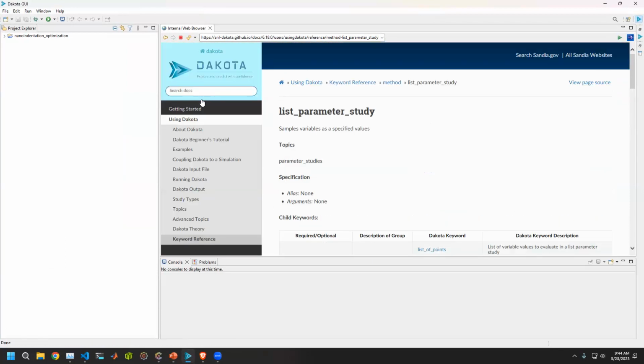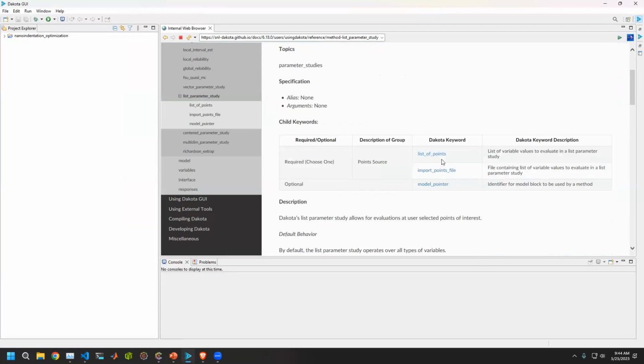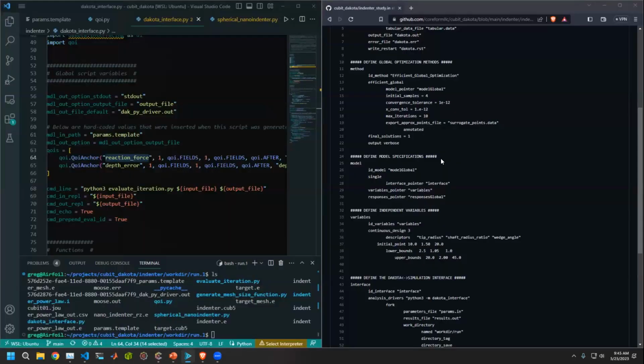But if I specifically have maybe 35 specific models I want to run, I can just put them in as a text file or as a list of points and just let DAKOTA handle all of the directory creation and cleanup. So that's really what I wanted to show, that there's a lot of functionality within DAKOTA that could probably make everything I've shown even easier. But with Python, just about anything's possible. I've at least found that this workflow works for me as far as being able to update a template from study to study. So hopefully that helps answer your question.